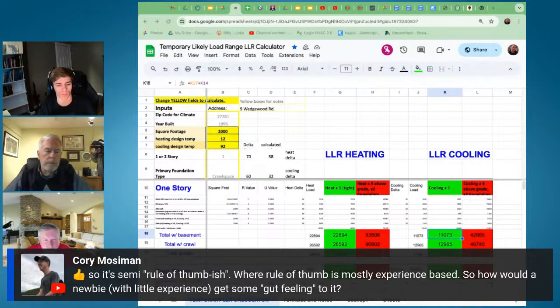My understanding is it is a Manual J with worst case infiltration and best case infiltration. Yes. Well, that's the biggest piece, but it might not necessarily be just that, because there's other factors as well that you may or may not know. Like, for example, you go into an older house, how are you checking R value in the walls? You can look and go, okay, when was the house made? Well, the code at that point in time was R11. Was it R11? Without opening up a wall, you won't know.